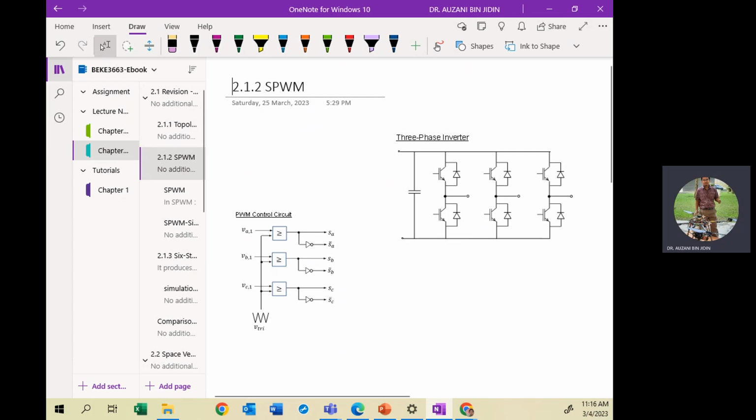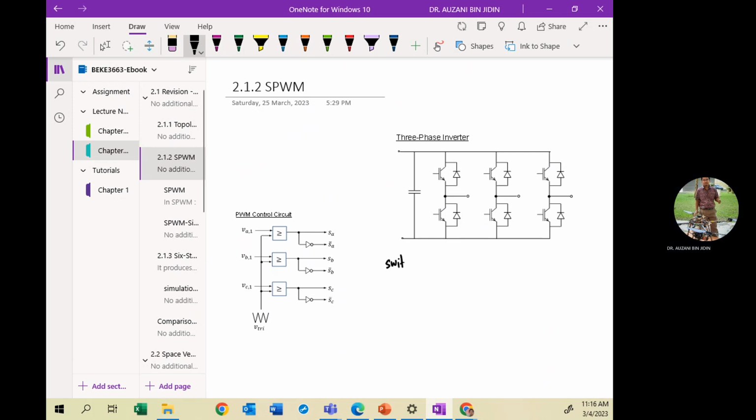So we can write the expression for the switching states for PWM. Sorry, before that, we have to define the switching state of the power switch. Here it will be SA, because it is leg number 1, phase A. For the bottom, because the switching must be complementary, you put a straight line on top of the letter. This means the signal is the inversion of the SA status.